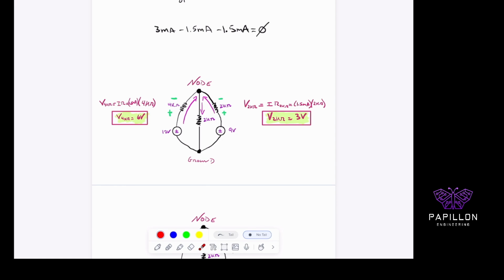And again, for this right branch, it's 1.5 is what we solved for. So it's 1.5 here, 1.5 here, it's 1.5 everywhere on an isolated series portion of your branch. So here to here, it's series, okay? So it means it's 1.5 milliamps the entire way through. Because of that, 1.5 milliamps times 2,000 ohms gives me back 3 volts. So I get back the 3 volts going across that branch.